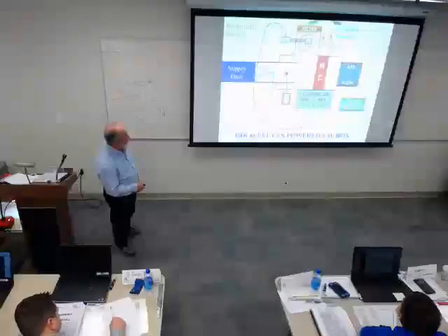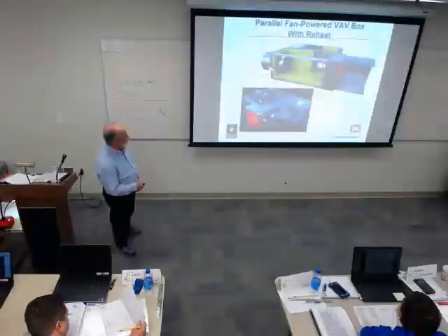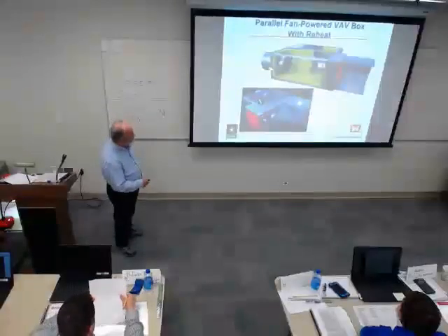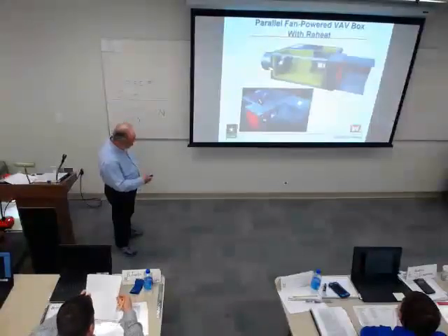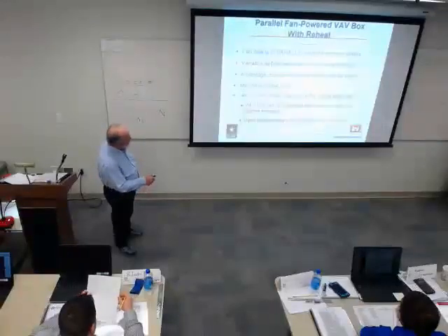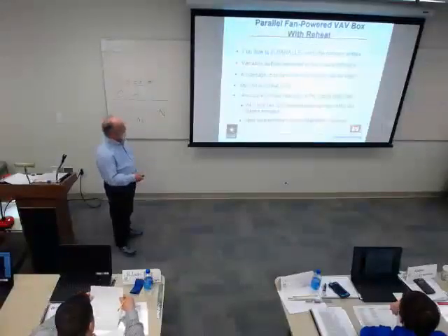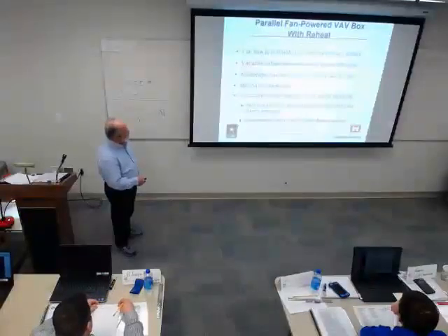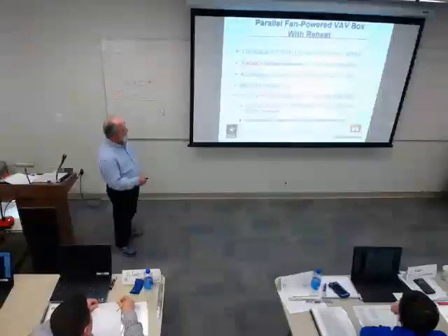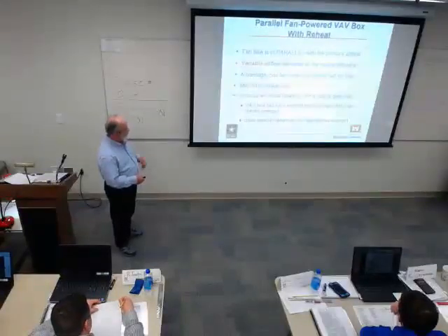And there's a backdraft damper. Better have motorized ones. And there it is, this one right here. Well, this right here, you can see the fan a little better. So the fan is parallel with the primary air connection to the box, and the air that's delivered is variable.